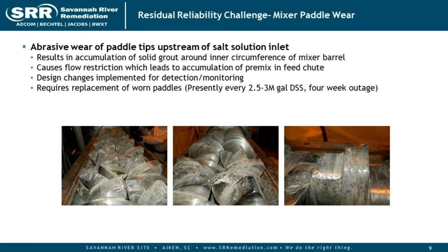Now, this doesn't have an immediate impact on the mixer itself. The mixer is going to continue to move material and blend very well. But what it does is it creates a gap between that eroded paddle tip and the wall. And I showed you on the clean picture how narrow that gap normally is. As that gap continues to open up, you will get an accumulation of solidified saltstone that adheres to the wall of the mixer itself.